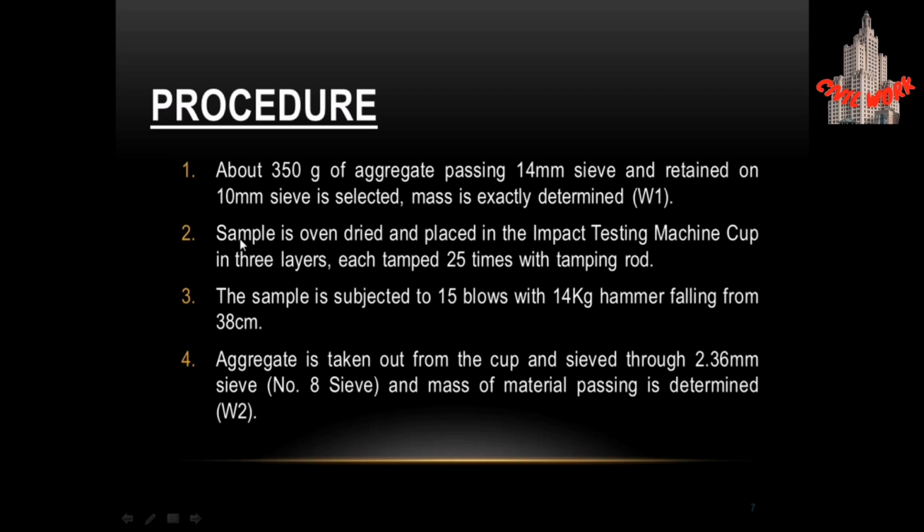Point number 2 is that the sample is oven dried and placed in the impact testing machine cup in 3 layers, each tamped 25 times with the tamping rod.